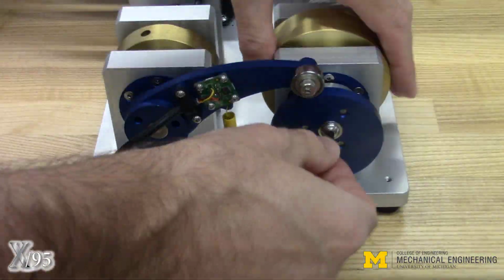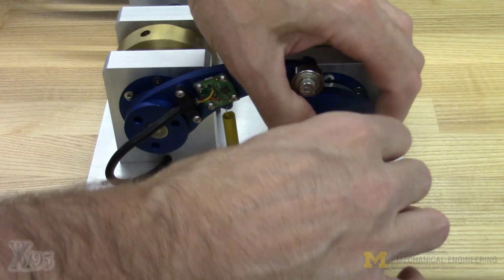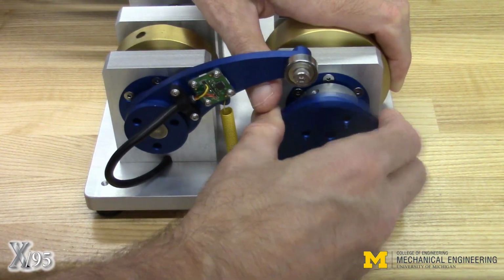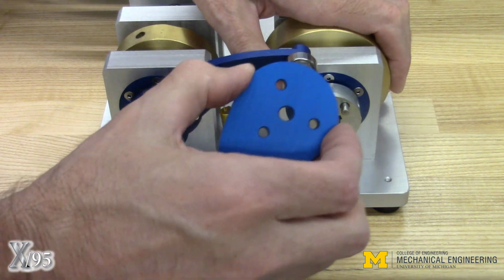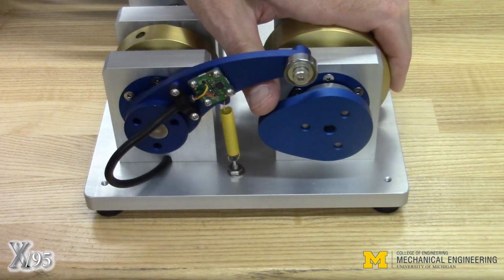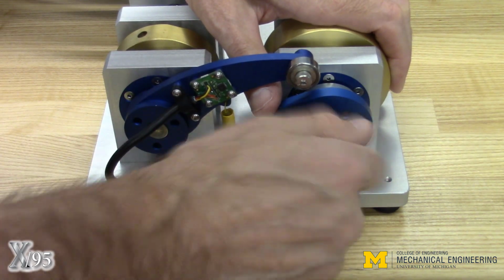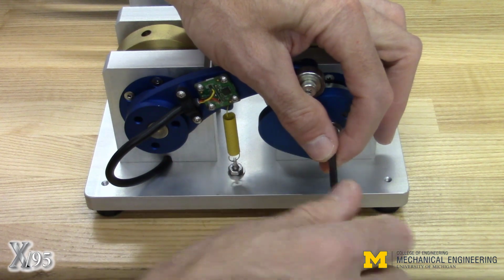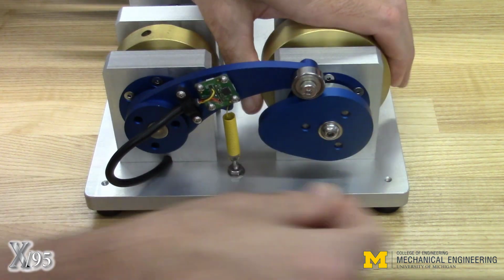To change the cam, loosen the center screw with the provided Allen wrench and gently ease the cam off the dowel pins. Orient the holes of the new cam with the dowel pins and slide forward against the hub. Then reinstall the 1/4-20 screw and gently snug it. Don't over-tighten.